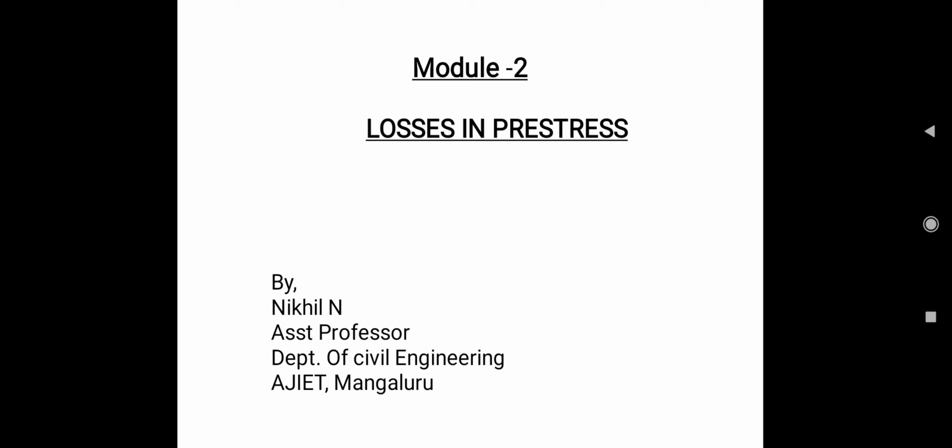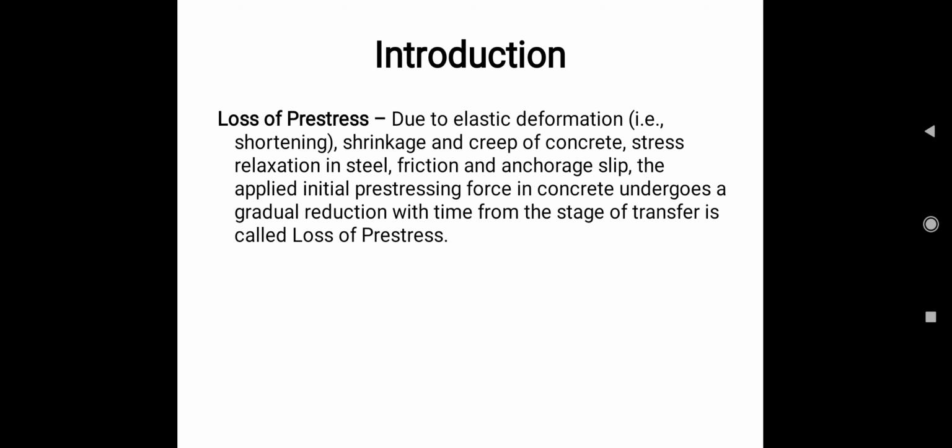So today I am doing this video to explain about losses in prestress. What are losses in prestress, and why do we need to know the amount of loss in prestress? In prestressed concrete, the most important parameter is the prestressing force. If the prestressing force reduces with time, then the prestress also gets reduced.